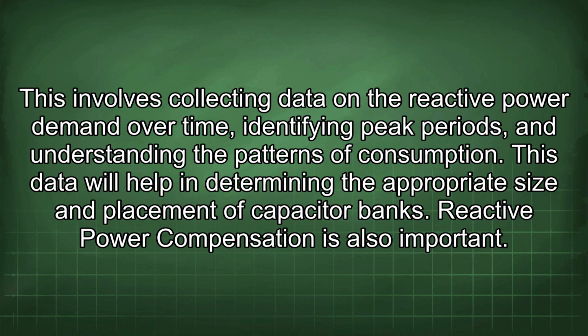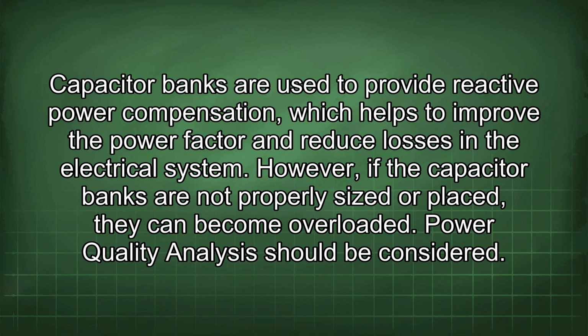Reactive power compensation is also important. Capacitor banks are used to provide reactive power compensation, which helps to improve the power factor and reduce losses in the electrical system. However, if the capacitor banks are not properly sized or placed, it can become overloaded.